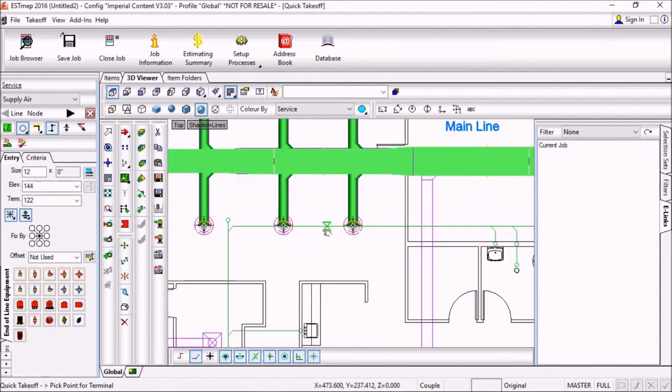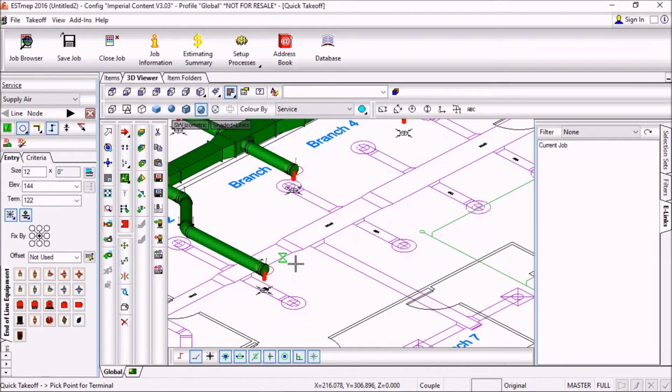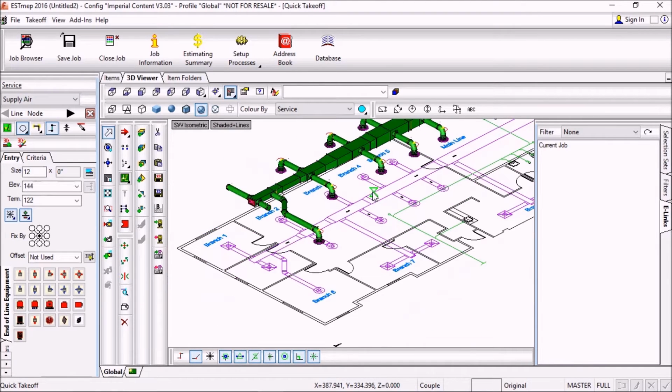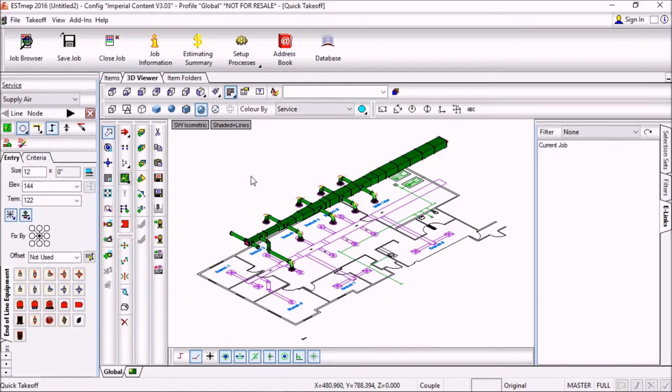Okay, so going to our 3D view here, I'm just going to switch up to a 3D view. You'll see that they don't look three-dimensional yet, but there is a really great fill-in 3D tool here where you could click on it and then it'll update it with the new 3D diffusers. So in this scenario here, we manually drew it ourselves because we didn't have a Revit model, a nice smart Revit model to steal information from.